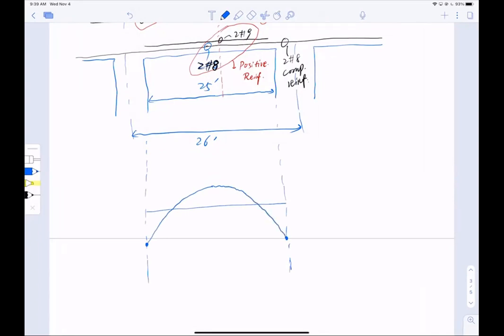And now I have the moment here, which is minus 225 kip-feet. What did I tell you? A negative bending moment. At the top here, I have 162 kip-feet of positive bending moment. And just in case you forgot, this is IE2, this is IE1, and this is IE middle. All right, so this is the bending moment.